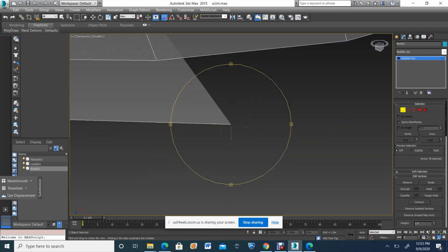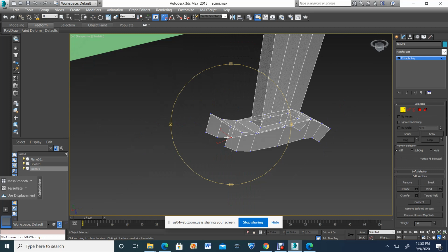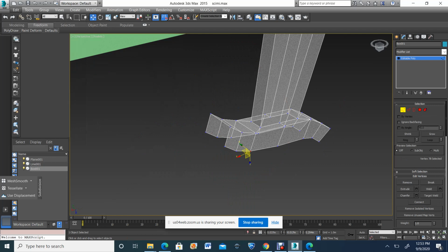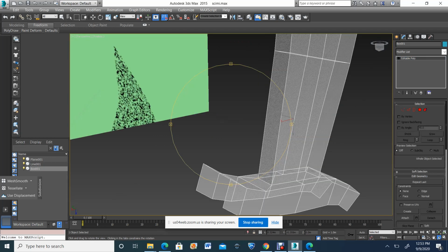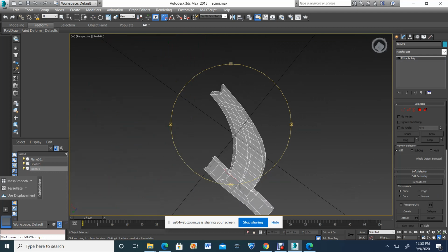I will press Z to, again, go back to my object. And then I'll go ahead and select the other one. Select those 2 vertices selected, and weld. And I'm going to save. Control S. So now I want to connect those bottom vertices of that hilt so they're a little bit enclosed.